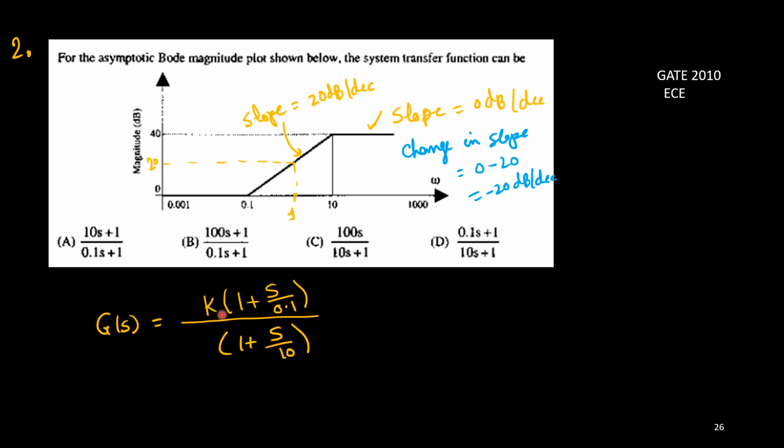No need to find out the k, and k will be 1. Why? Because the initial gain is provided as 0 dB. Means there is no level shift. Thus k equals 1. So if initial gain is 0 dB and there is no slope, then obviously k equals 1. And if it is other than 0 dB initial value, then it is due to some constant k. Okay, we need to find out that value, right?